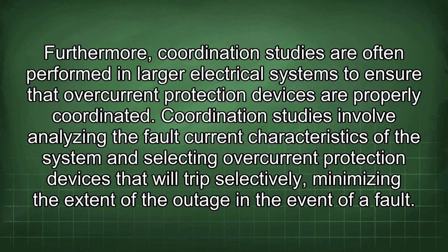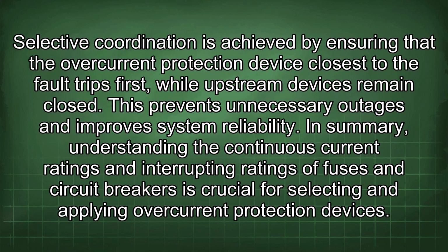Furthermore, coordination studies are often performed in larger electrical systems to ensure that overcurrent protection devices are properly coordinated. Coordination studies involve analyzing the fault current characteristics of the system and selecting overcurrent protection devices that will trip selectively, minimizing the extent of the outage in the event of a fault. Selective coordination is achieved by ensuring that the overcurrent protection device closest to the fault trips first, while upstream devices remain closed. This prevents unnecessary outages and improves system reliability.